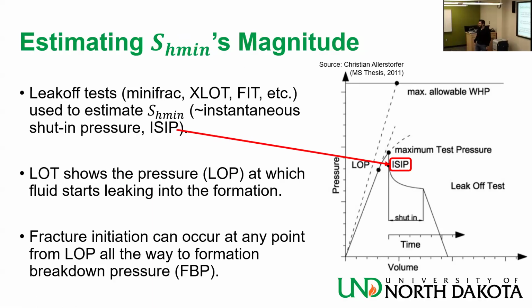It's like I'm raising the pressure to what I think will be the highest pressure that the well will see, that section of the rock will see before I case it, and test if the well can hold that. It's a little bit different than leak-off test, in which I intentionally get to the point where the well starts leaking just before breaking, and so on.